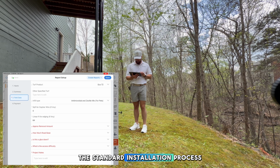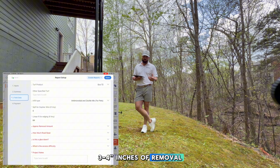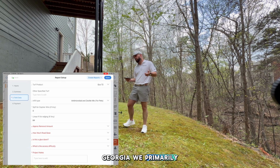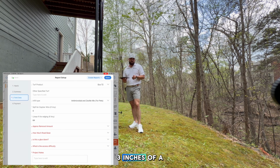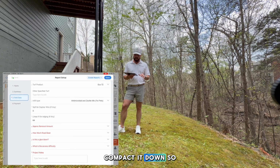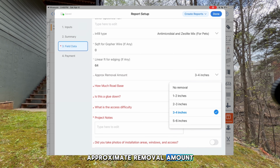The standard installation process is 3 to 4 inches of removal of soil or sod, whatever is there, and 3 to 4 inches of our base. For instance, in California, it's a class 2 road base. Georgia, we use like 3 inches of a crusher run and 1 inch of sand on top, compact it down. So approximate removal amount, 3 to 4.